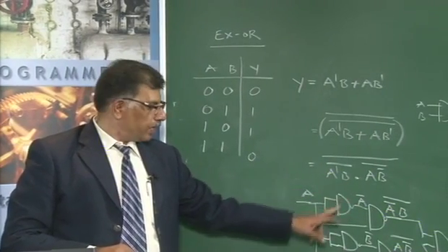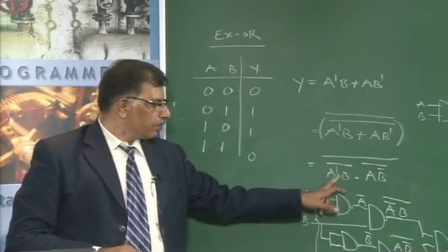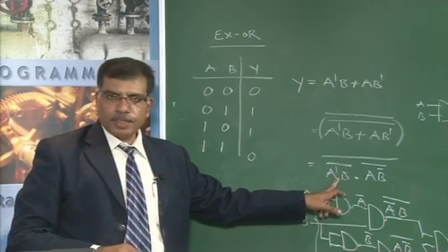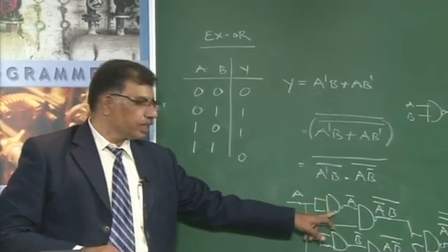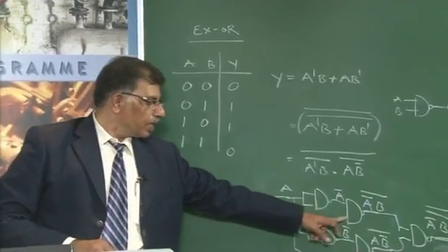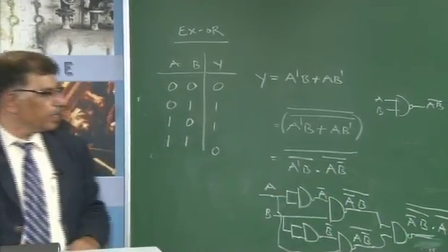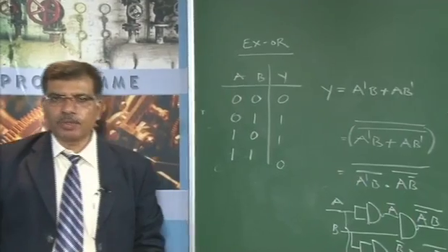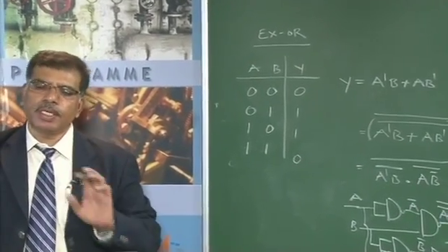Keep it as it is and realize this expression. If a complement is there on the logical variables, use the same NAND gate and connect like this, so that you will get the entire exclusive OR expression by using only the NAND gate.